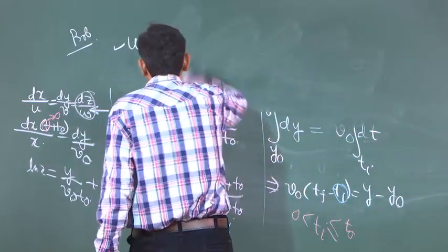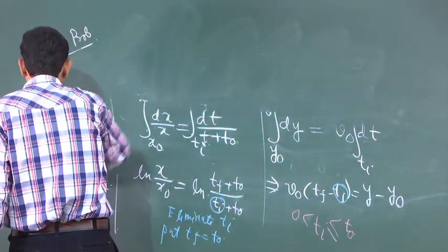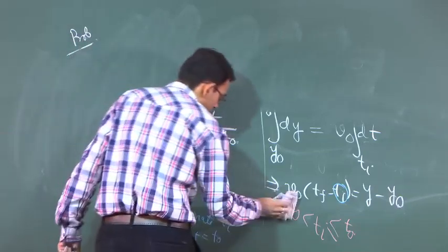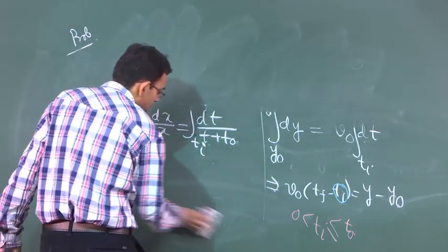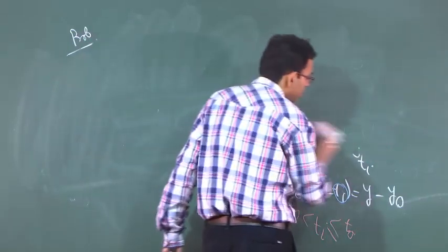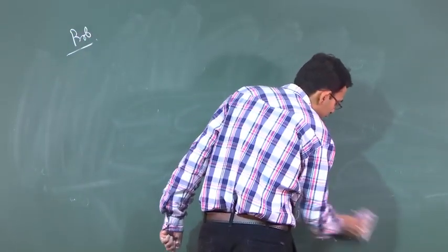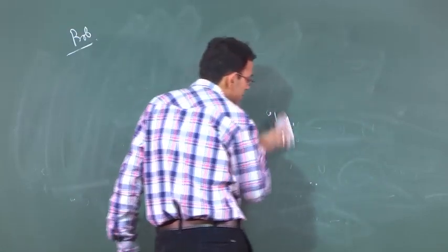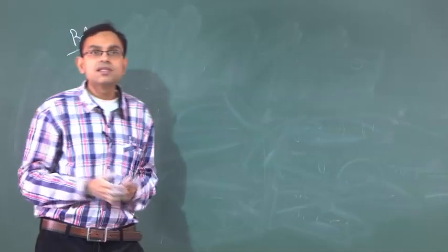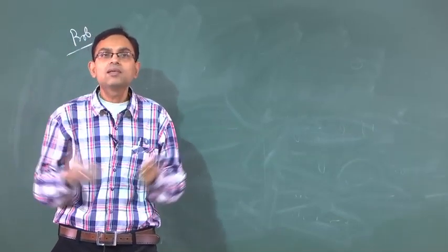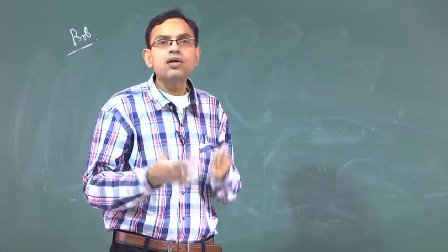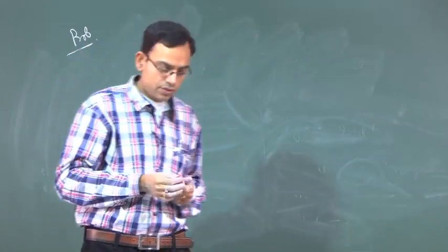So, with some kind of description of the flow field, next we will try to understand the various strains in the flow field, and that is where the real fun of doing kinematics is. For solids it is the strain that is important, for fluids it is the rate of strain or rate of deformation that is important.